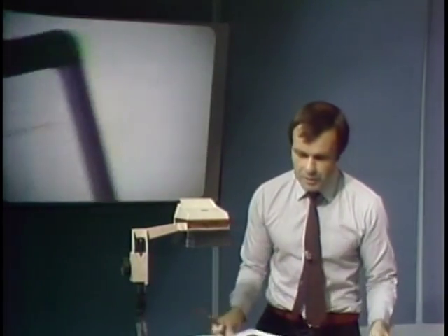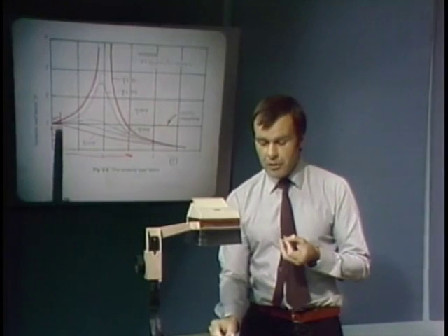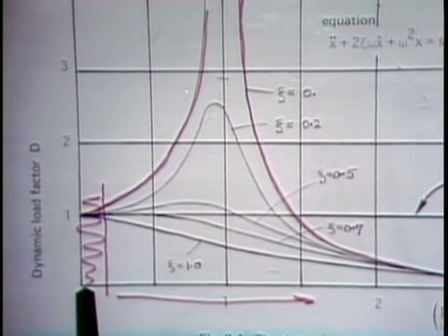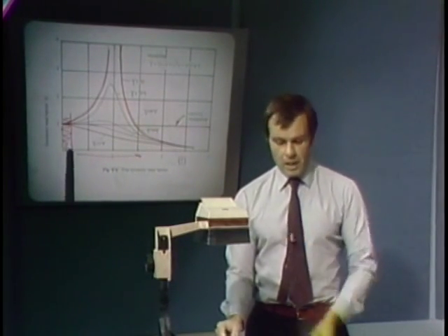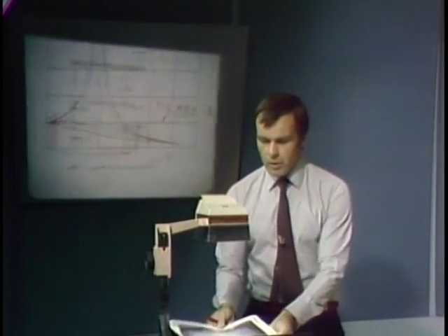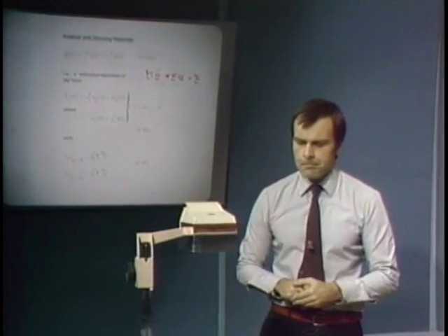If that highest frequency divided by the frequency of the system falls into this range here, we are talking about a static response basically, and we do not need to consider that equilibrium equation in our mode superposition analysis.